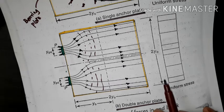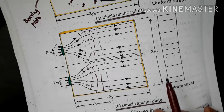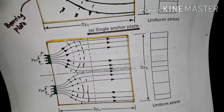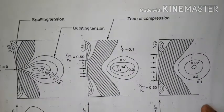So this is regarding how important the anchorage zone is in post tension beam sections, and how the tensile stresses, the transverse stresses and the longitudinal stresses are developed at the end of the section where the anchorage system is provided in post tension beam sections. I can show you one more diagram here. I think all three sketches are visible here.